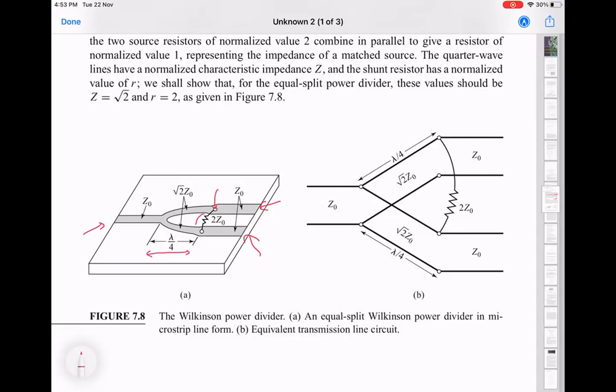Yes, but essentially a port is where power can be delivered, right? A port is actually dissipative. It's basically 50 ohms for a 50 ohm system. This is not a 50 ohm port, but it's a resistor. So I could, in principle, have, it's tricky to make, but I could have made a 2 Z0 transmission line and taken it out through the third dimension. That would be a transmission line which has the two terminals on either side of these things. And then I could terminate it with a 2 Z0 termination. So it's not a 50 ohm port, but it's a hidden fourth port.